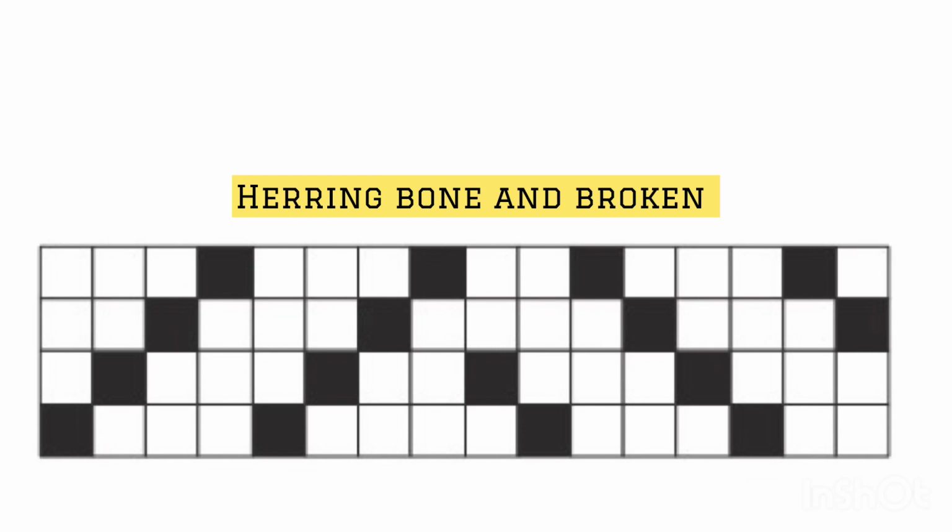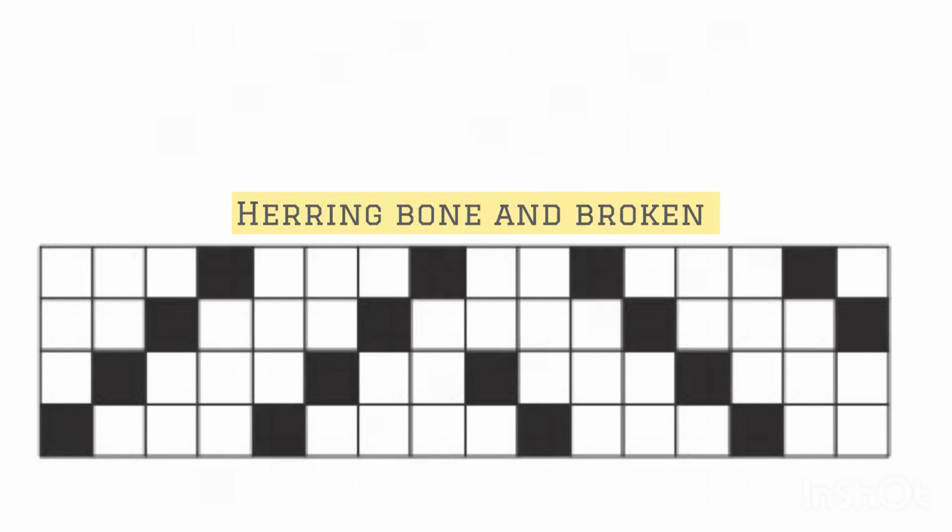So next one is a broken draft. This draft may be considered as modified pointed draft. It is also a combination of straight drafts of different directions of construction. In broken drafts, a break in continuity occurs where the warp thread reverses its direction. This direction is reversed not on the last or first shaft as in pointed draft. The broken draft is applied for producing herringbone, twill, etc.